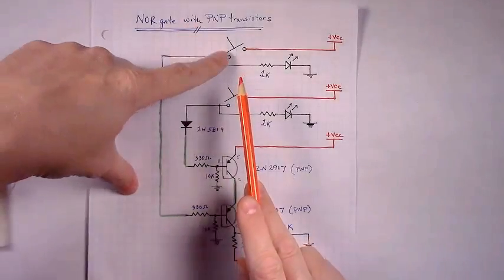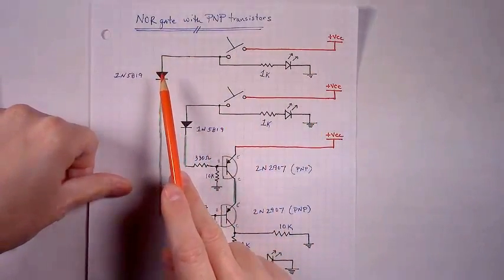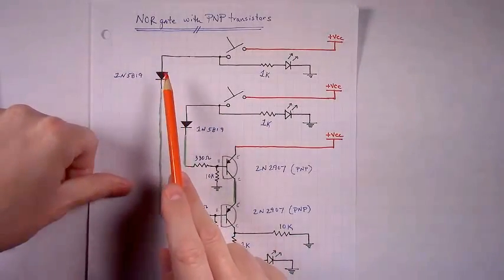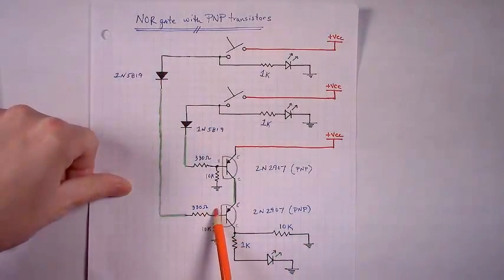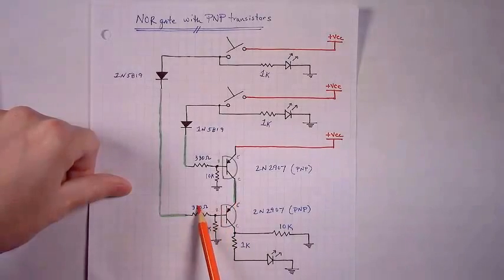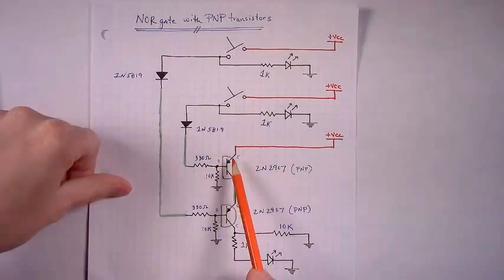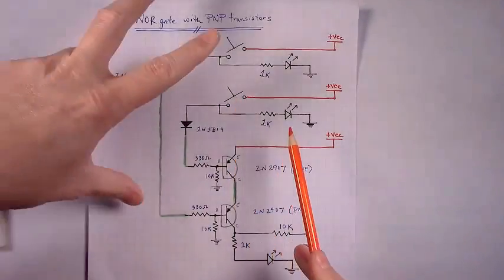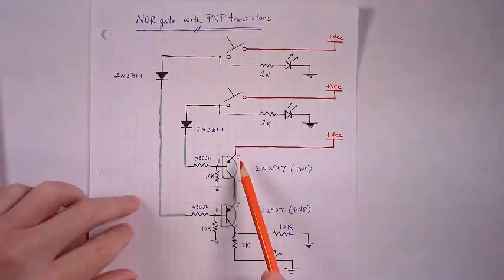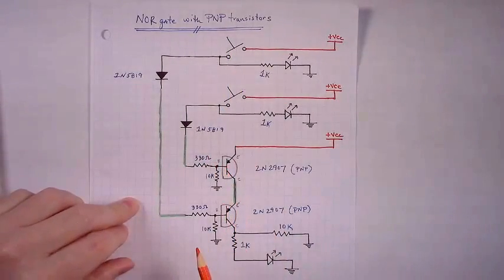When you push the first momentary button, VCC travels, you lose a few tenths of a volt, and it goes down. There's still enough voltage left to raise the base of the PNP above that 0.6, 0.7 volt threshold that's required for the PNP to conduct. So you cut it off. It stops conducting. The same story plays out when you push this momentary button or when you push both of them. You're essentially, when you push a momentary button, shutting the PNP off.